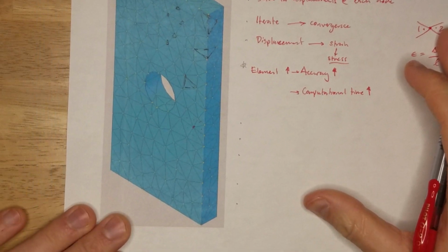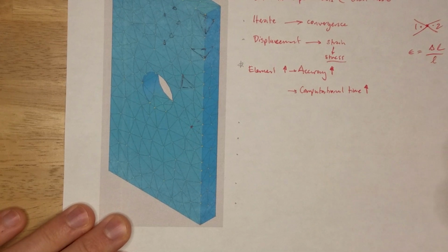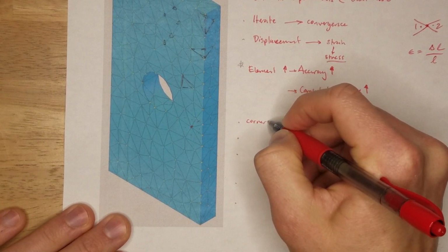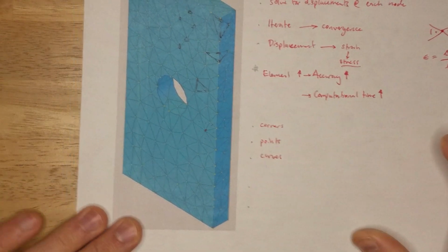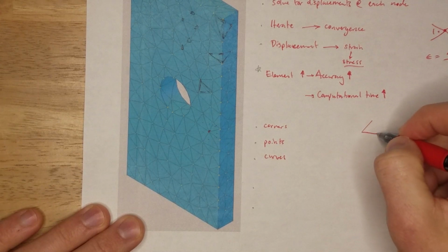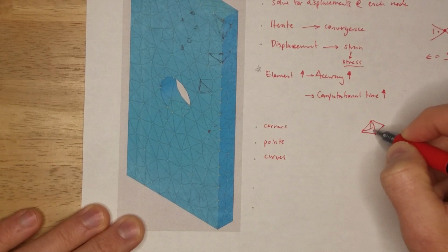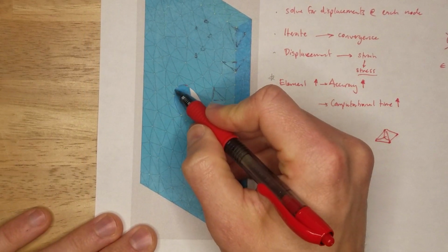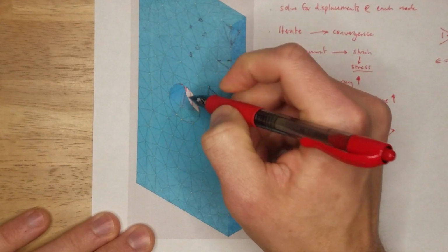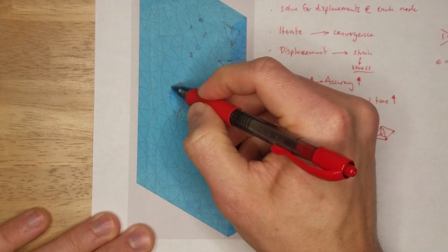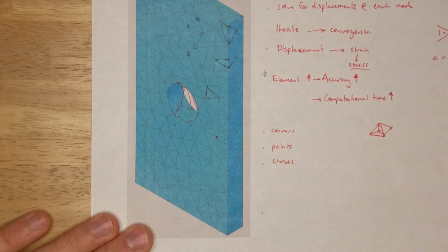Now, meshing is an approximation. That's the key. And so it has some limitations. It's really not great at approximating corners, points, or curves, specifically curves. Think about that. We've got an element that's got sides, flat edges, and we're trying to approximate a curve with flat edges. That's going to be difficult. And you can even see here, we've got some very big elements next to some really small elements. They're not equally spaced here either, so that's a good example. Sometimes meshing is not perfect at approximating a structure.